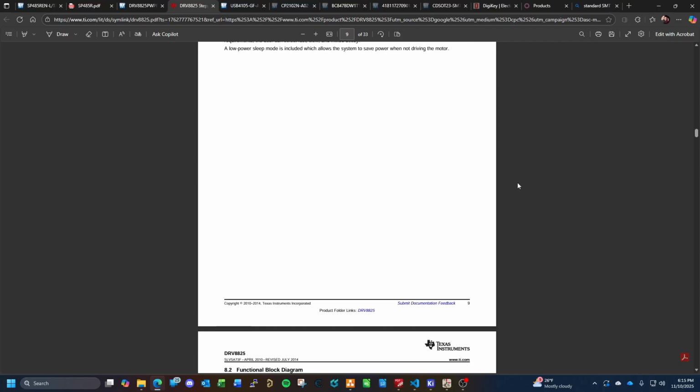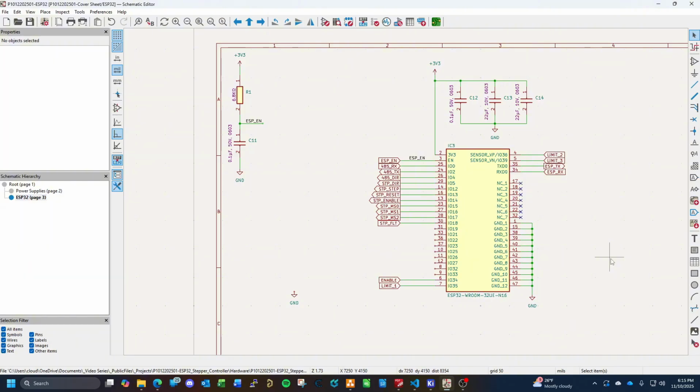All my testing with this has shown it's really not super important to me, and that would complicate the design. Using a couple ADC inputs, we could technically monitor the current between the motor windings to catch an overcurrent condition, using something like a current sensing resistor.